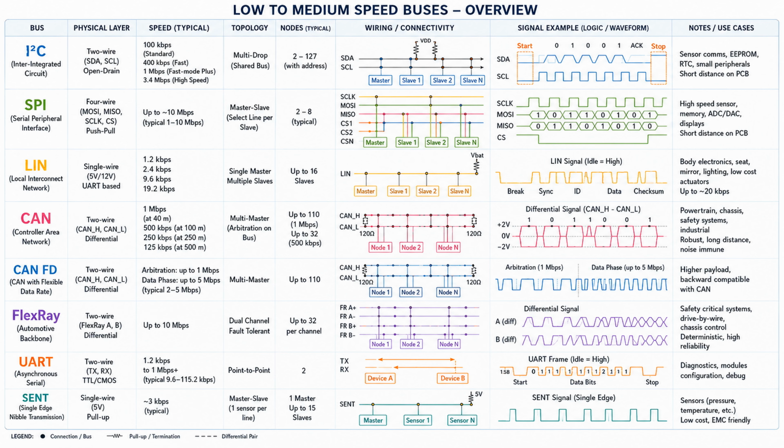Section 4 describes CAN, Controller Area Network. CAN revolutionized automotive networking. It uses a differential two-wire signaling system, CAN high and CAN low. Differential signaling provides excellent noise immunity and long-distance reliability. CAN supports multi-master arbitration, message prioritization, fault detection, and automatic retransmissions.